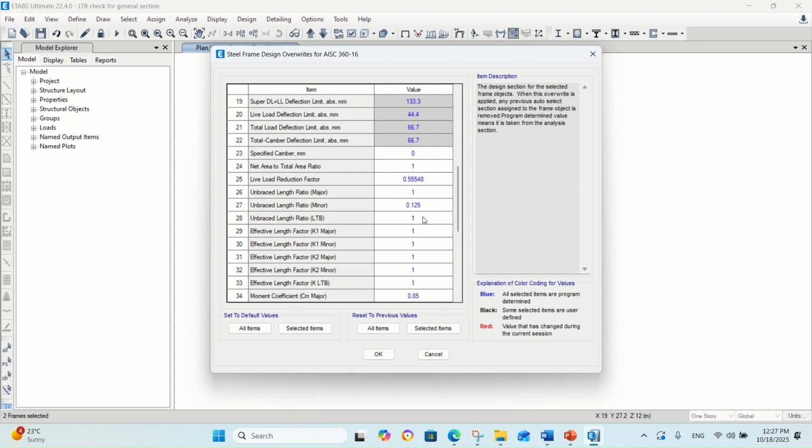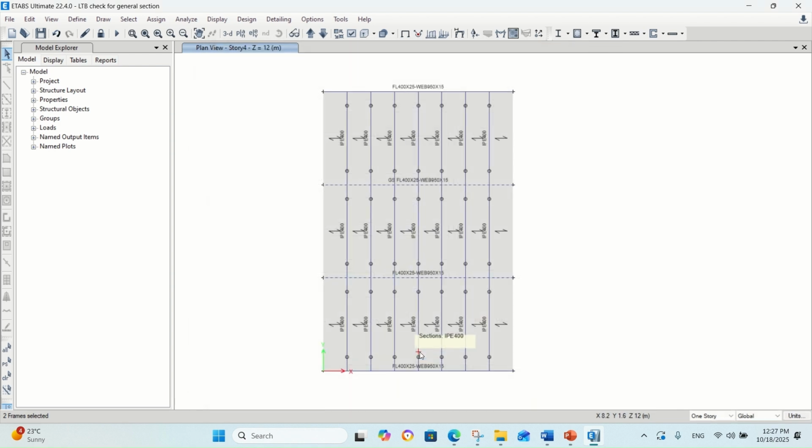And you will see now why we are using the assumption that the secondary beams are not bracing the main girders. However, generally in floor, especially if we have a composite concrete slab, the secondary beams will brace the main girder, especially if it's simply supported girder.